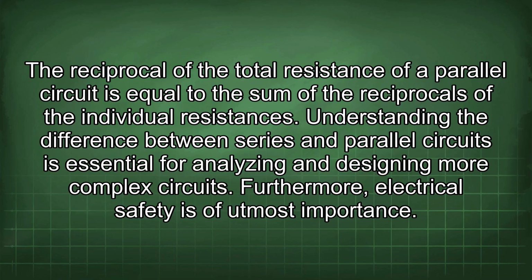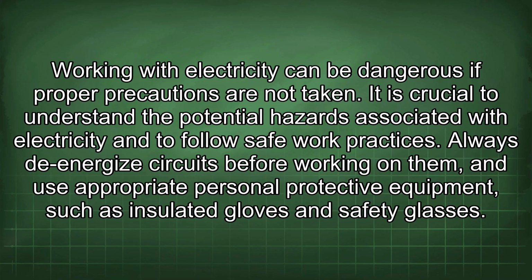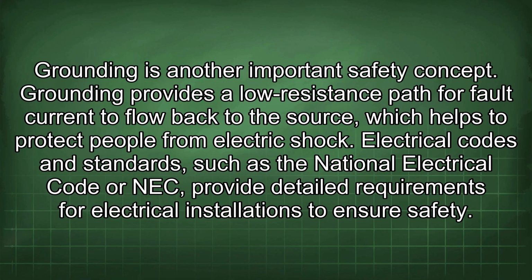Furthermore, electrical safety is of utmost importance. Working with electricity can be dangerous if proper precautions are not taken. It is crucial to understand the potential hazards associated with electricity and to follow safe work practices. Always de-energize circuits before working on them, and use appropriate personal protective equipment such as insulated gloves and safety glasses. Grounding is another important safety concept.